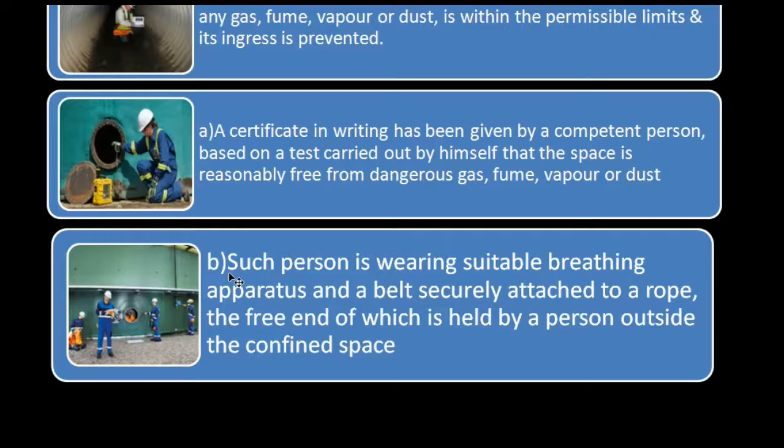Clause B. Such person is wearing a suitable breathing apparatus and a belt securely attached to a rope, the free end of which is held by a person outside the confined space.